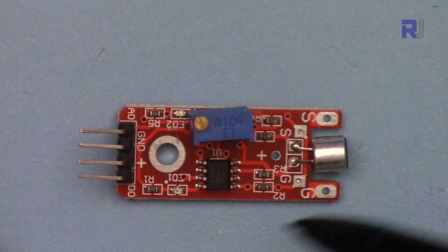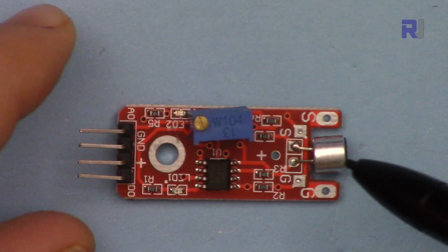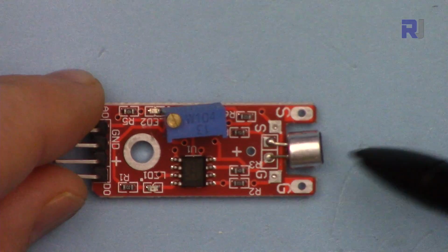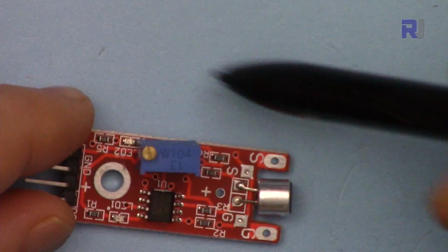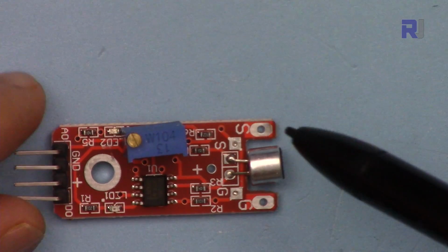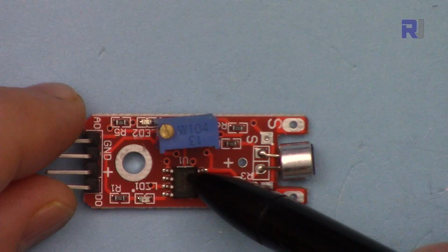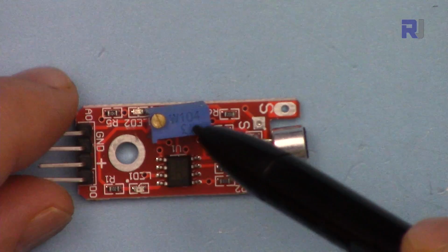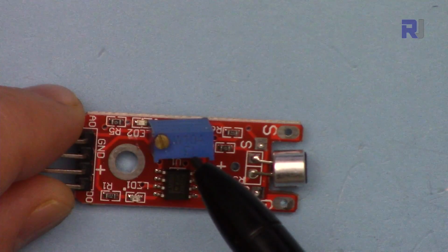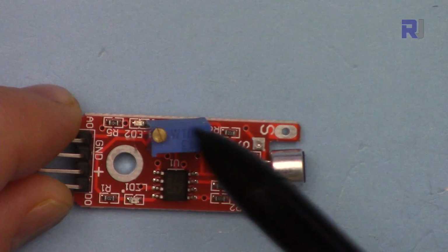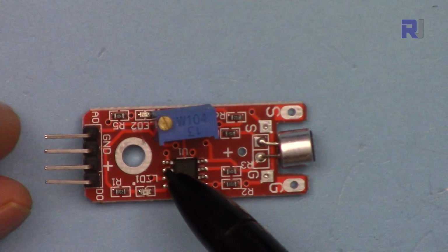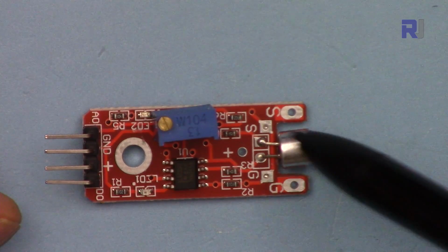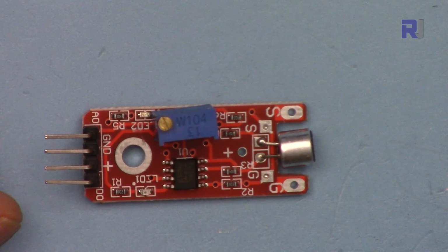In this lecture, we are going to learn about the sound module or sound detector. This module has a microphone here that picks up the sound surrounding the module, especially from the front, but it has a pattern that it can pick up sound from everywhere. The sound is then amplified, and the sensitivity of this microphone is adjusted using this multi-turn variable resistor or potentiometer. This is a 104, 100 kilo ohm potentiometer, and the detected output will be sent to the Arduino, and based on the detection of a signal or sound, we can take some action.